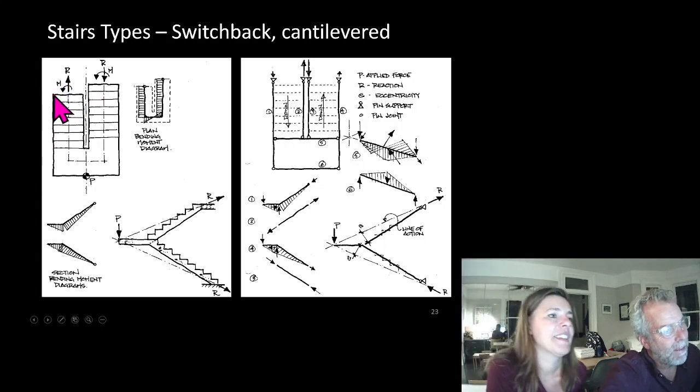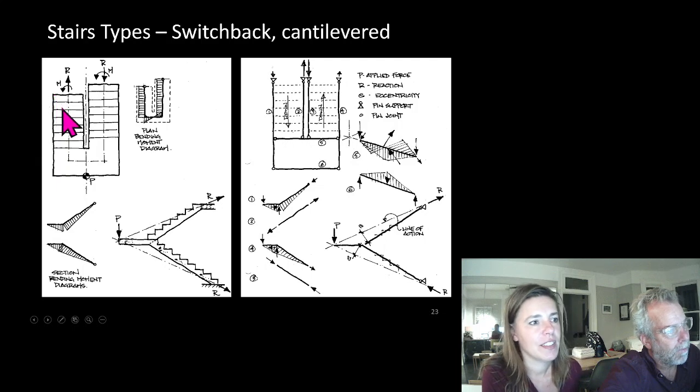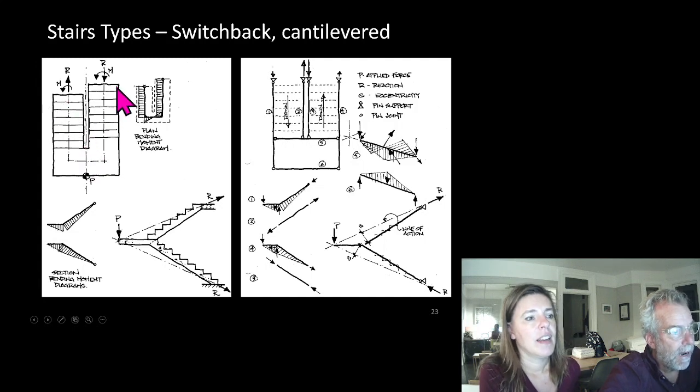Imagine this as a load path. Diagonal here to that point, diagonal up here to this point. That now is a 3-pinned arch. We have a fixed point, we have a fixed point, and we have a supported point right there. So this point right here is fixed in space by a 3-pinned arch. Everything else is derived from that.